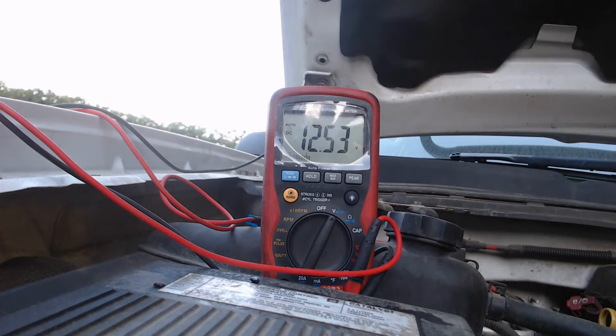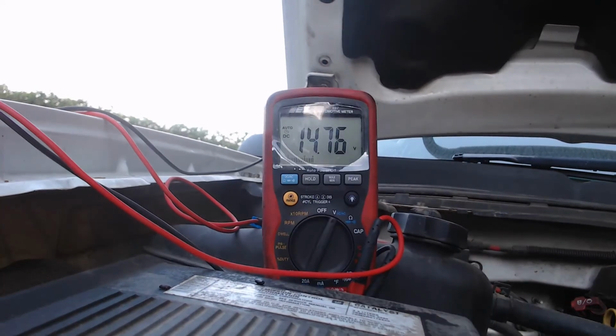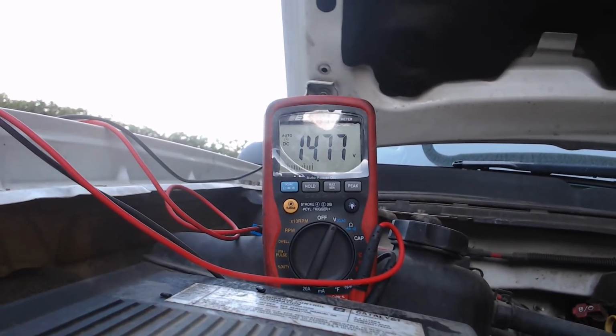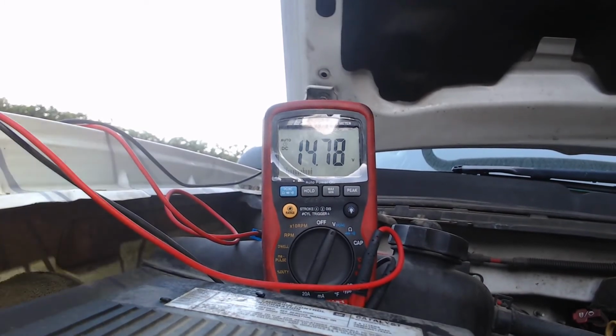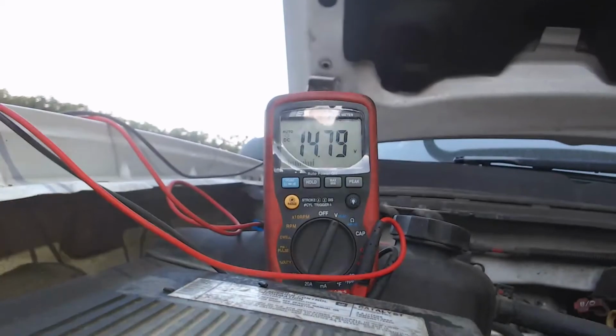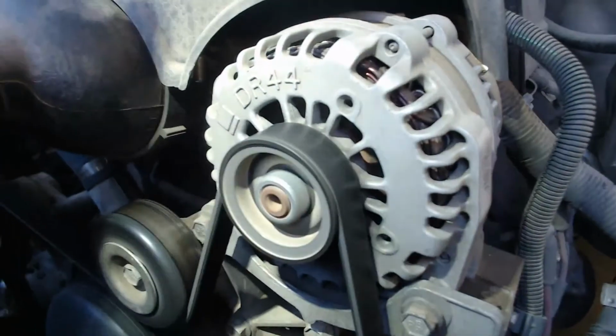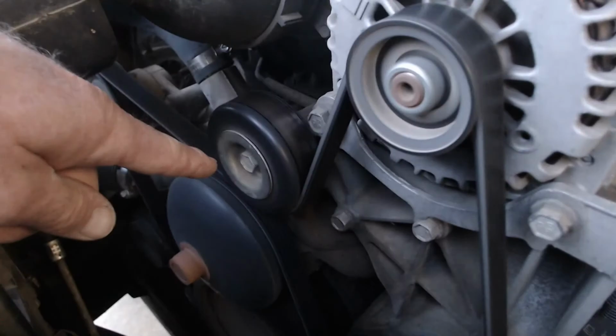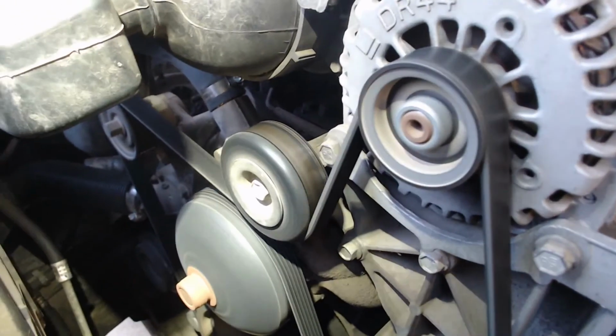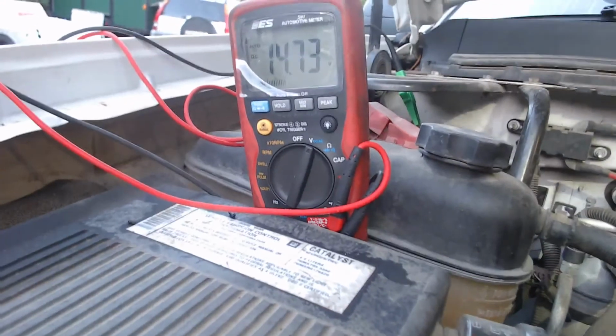So here we go. I'm starting the car up right now. So you can see on the screen that the charging system voltage is 14.77, 14.78 volts. So it appears that this thing is charging. And you probably can't hear it very well, but we are getting a little whining out of this alternator, sounds like the buzzing out of the alternator, which is fairly normal. Sometimes this idler pulley makes a little noise. The belt's a little dry, it does need a belt. It is interesting to note that this 07 uses 2 electric fans and not a belt-driven fan, which is kind of interesting. And yes, it needs a pressure wash and needs to be cleaned up, and we'll be doing some of that. So our charging system voltage is sitting around 14.8 volts. So it looks like it's charging.